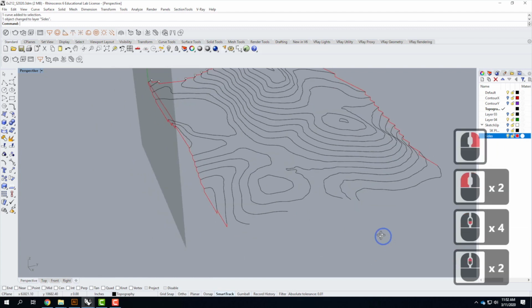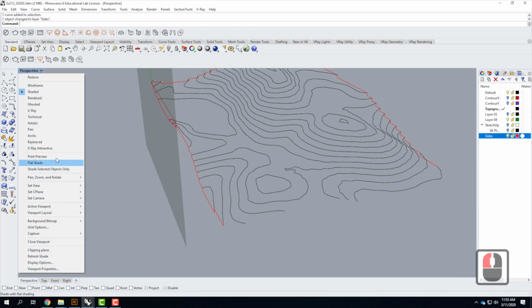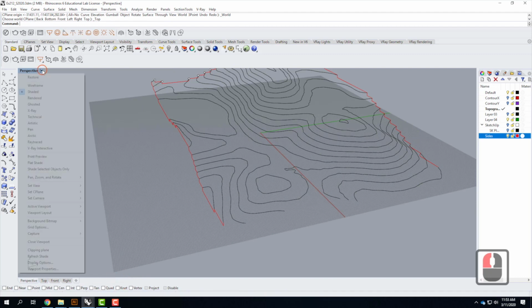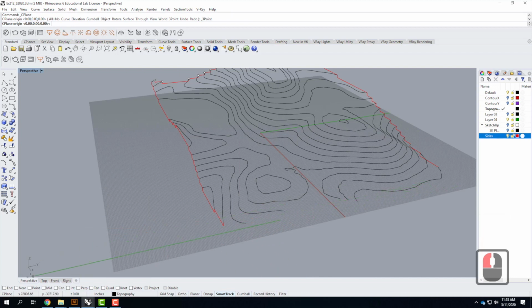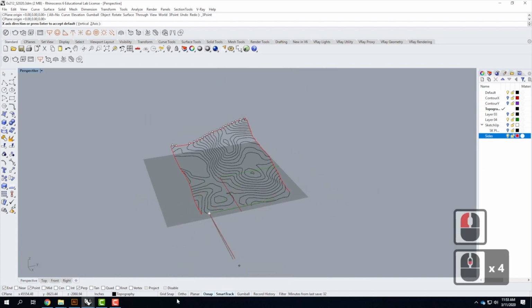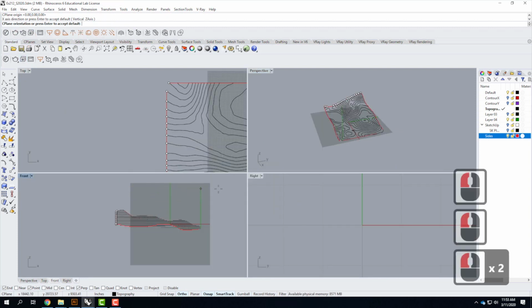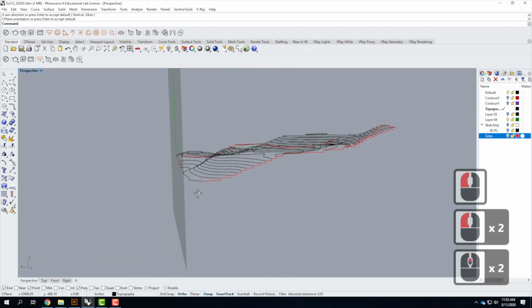Like that. I didn't do this front piece here, so I'm going to change my C-plane. I'm going to go to Set C-plane. Remember, you always go back to World Top first. And then I'll go to Set C-plane 3 points. Let me snap to the end, to a point, and to perpendicular. And we'll go off in space. Let me turn on ortho. There we go. Let me go straight up and down. There it is, going straight up and down. Perfect. So I'm in the C-plane.